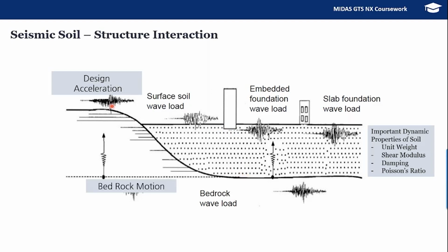We need to convert this design acceleration into bedrock motion. So you can apply the bedrock motion and then model the soil layers, and you can get the effect on the building. So this process of converting your design acceleration into bedrock motion is called deconvolution.